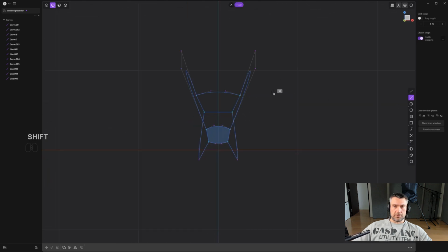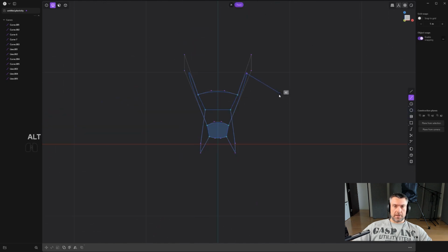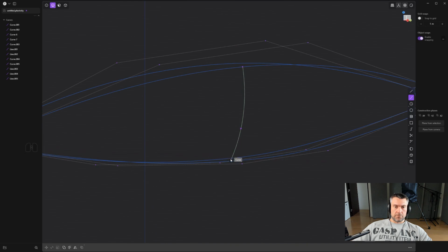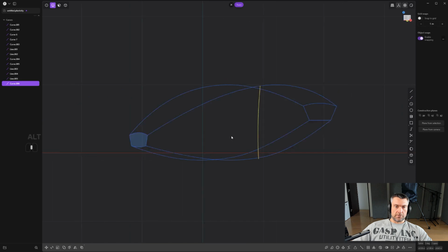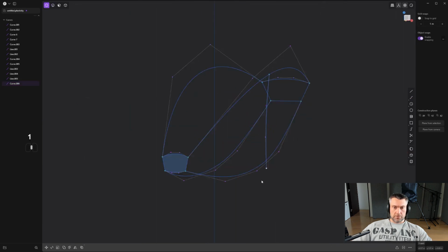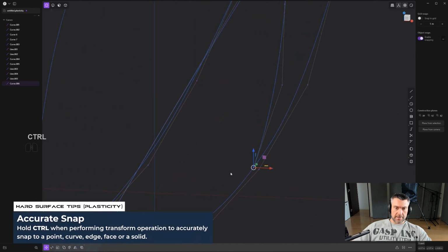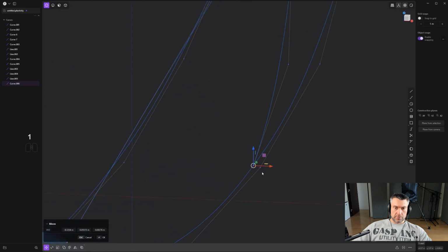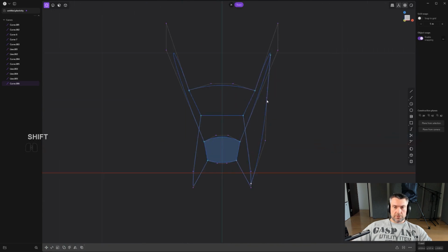So what we could do is grab this edge here, this curve, click somewhere in the middle and create kind of like a slightly curving situation here, and then go to the side view and click somewhere here and right click to confirm. And now let's just make sure this is connected. Yeah, so GG and hold control and make sure you connect it to this edge, right? Not to this control point. That's very important. Yeah, if you did, just delete it and redo it.